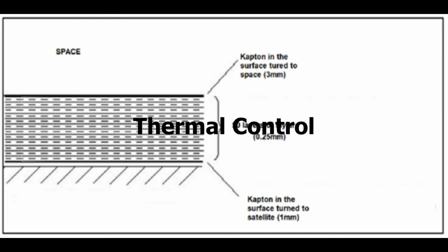Now about the thermal control subsystem, we've chosen for the coating the multi-layer insulator, composed by Kapton in surfaces of the satellite and Mylar with multiple layers, because it's used to reduce the heat exchanges by radiation between the satellite surfaces and the environment. This coating has low emissivity, 0.02, an effective absorption close to 0.05, and an effective thermal conductivity of 10^-4 watt per meter degree Celsius.